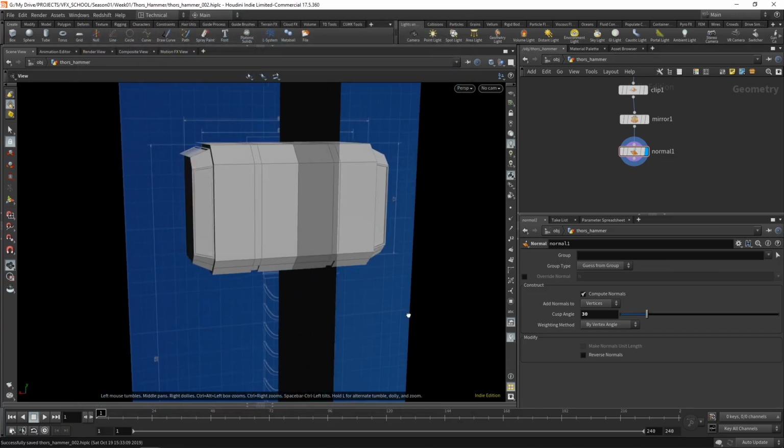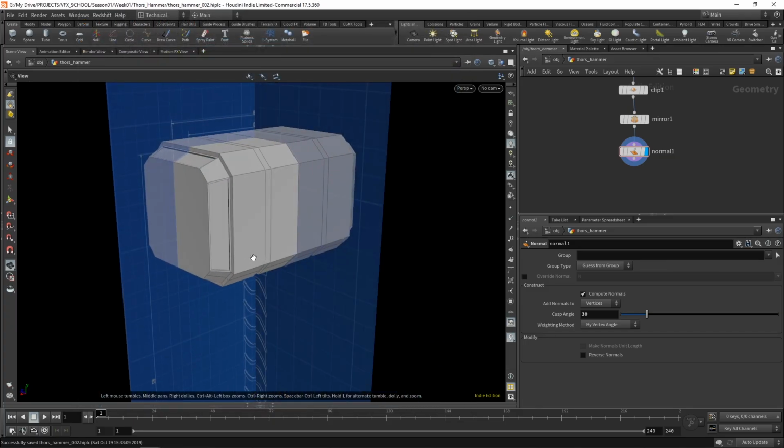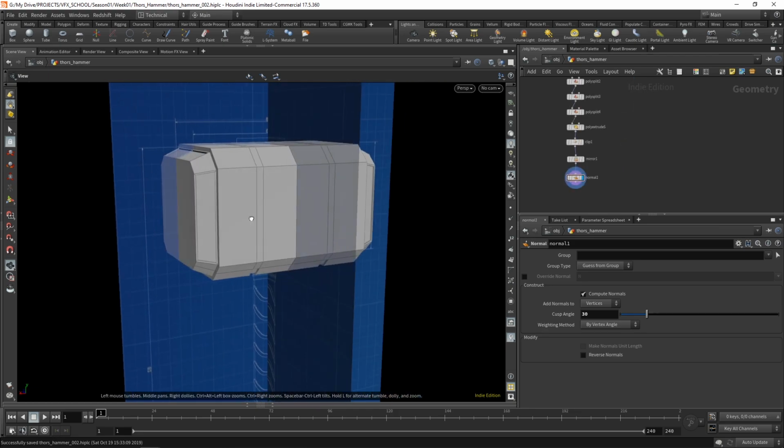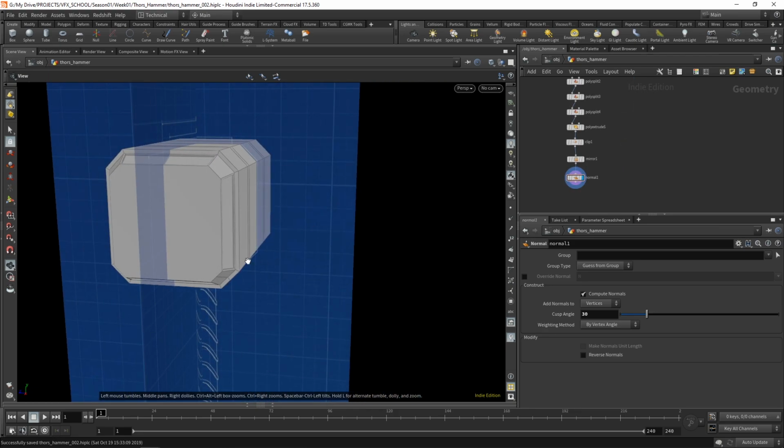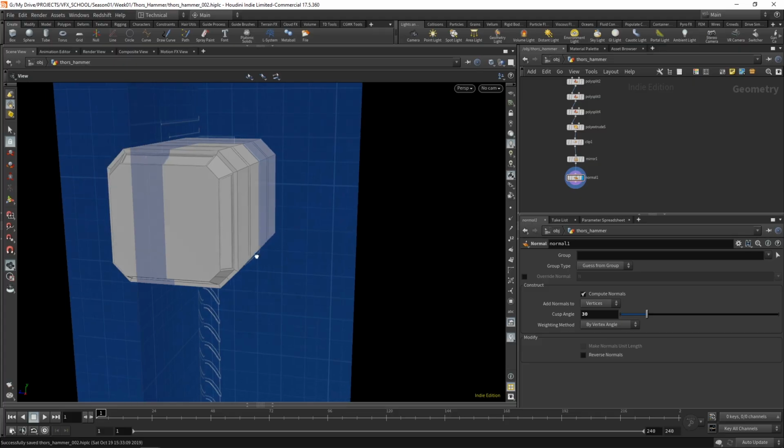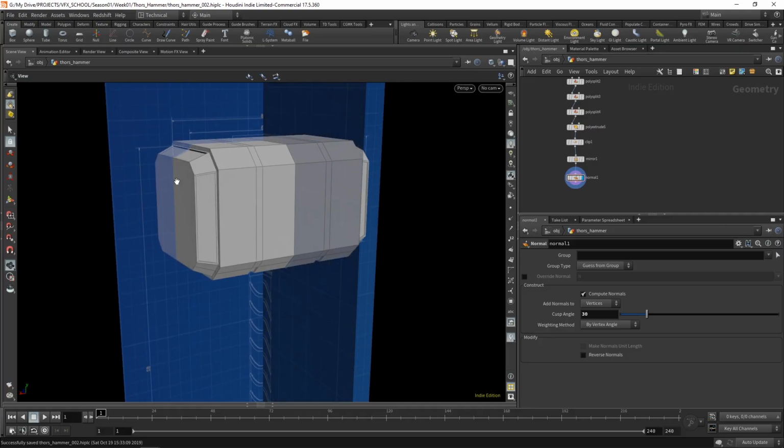The way I'm gonna do this will allow us to introduce you to some very useful nodes and techniques that are really powerful and kind of common on other 3D applications. So I think it makes sense for us to go over that. What we're going to be doing is basically applying a Boolean operation here on the side. We're going to be literally carving the sides with that shape. The Boolean system inside Houdini is absolutely amazing.